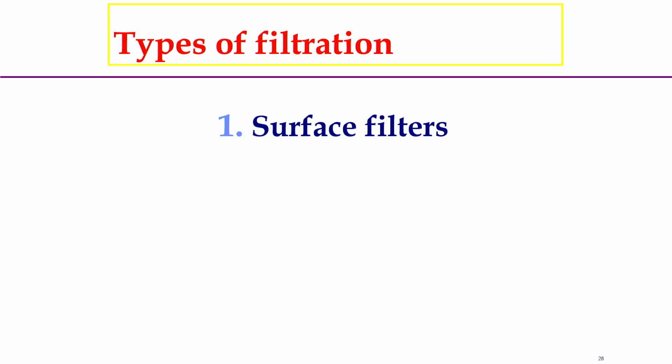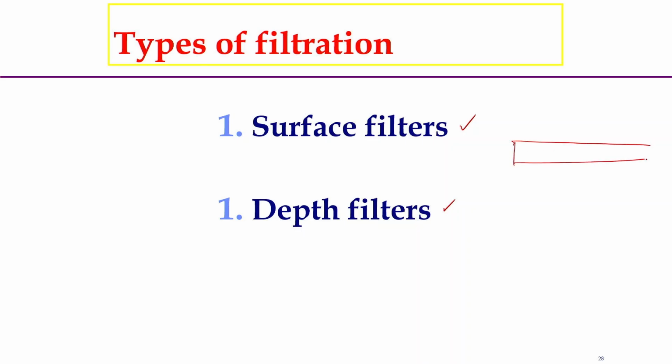One is surface filtration and another is depth filtration. In surface filters, the pore size of the filter media is less than the particle size, so the particles get settled at the surface of the filter media.